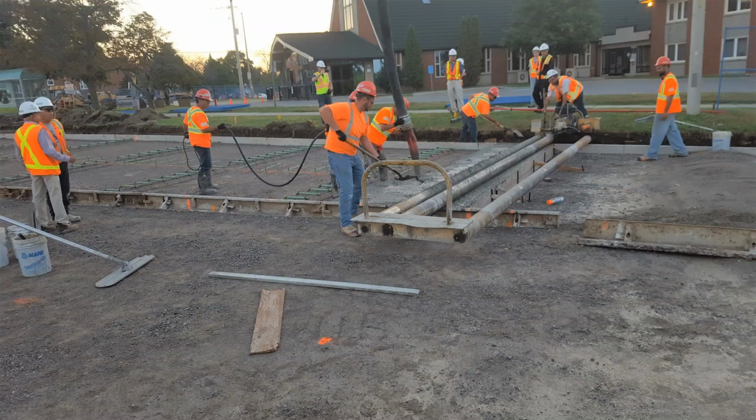This is the equipment that they used. The contractor used a vibratory roller screed. There's a few different types of equipment they can use. Often the slip form paver is preferred, but that's for stretches of highway where you're just going for kilometers of paving and it looks like a giant asphalt spreader. They couldn't really use something like that here because going around the radii and the islands, it just wasn't practical. So this equipment is a bit more mobile and more agile around the curbs and the islands. So you can see they've got all their dowel baskets laid out and they're just placing the concrete right over top and paving it with this roller screed.